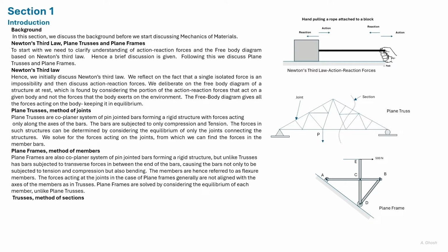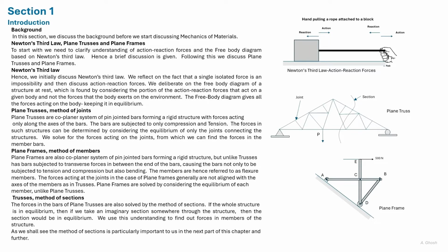Trusses are also analyzed using the method of sections. So if the whole truss is in equilibrium, then a portion of the truss will also be in equilibrium. We consider the equilibrium of a portion of the truss and find out the forces in the members of the truss. The method of sections is quite important since we will use it in other chapters.